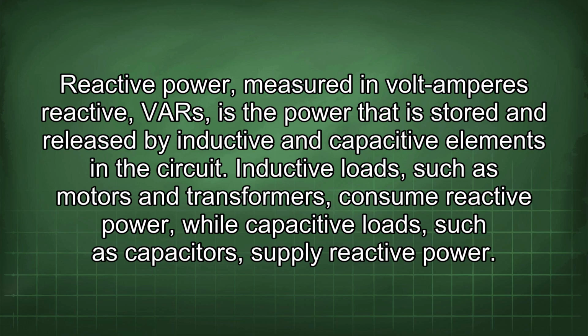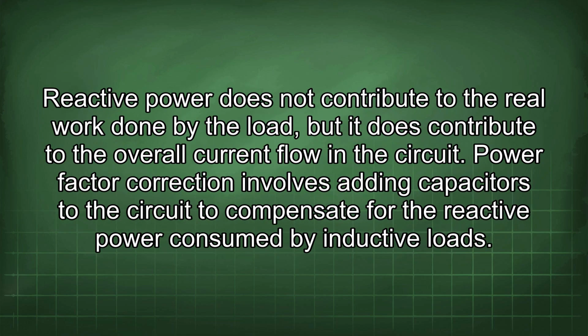Reactive power, measured in volt-amperes reactive, is the power that is stored and released by inductive and capacitive elements in the circuit. Inductive loads, such as motors and transformers, consume reactive power, while capacitive loads, such as capacitors, supply reactive power. Reactive power does not contribute to the real work done by the load, but it does contribute to the overall current flow in the circuit.